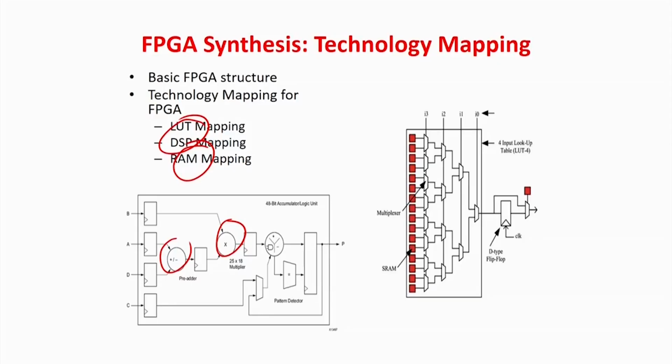So in this course there will also be dedicated lectures on FPGA synthesis optimization, because in ASIC or normal CAD everything has to be fabricated. Multiplier means you have to have a gate level multiplier, DSP means you have to implement the DSP, but in FPGA instead of basic gates there is something called LUTs, because FPGA has some kind of generic architectures available in terms of LUTs. You just need to do the interconnection so that you can get a circuit. So basically it is called a field programmable gate array. The same thing can be used for adder, multiplier. Tomorrow you can implement a processor, day after tomorrow you can make an image processing block, because you do not require any fabrication for that.